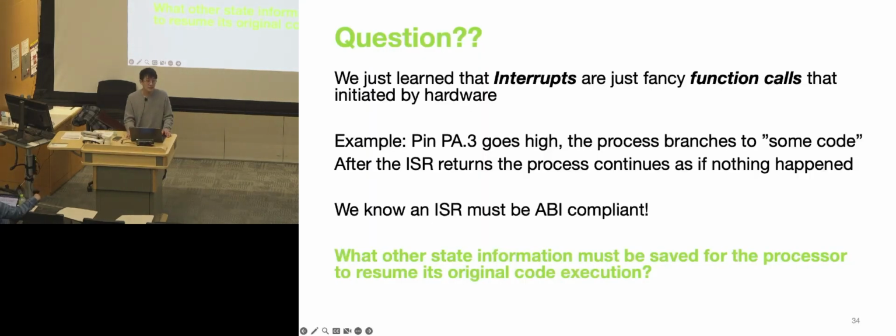If the interrupt controller sets the PC, how do you know where it goes there? That's a great question. So we should probably save it somewhere, right? So the PC, or register 15, is also something that will be saved in this case, different from the previous subroutine calls.